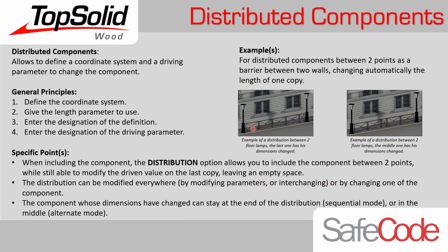You can modify the dimensions of anything in there. So when we bring the distributed components in, they're equally spaced. Every volume is the same width. We can modify that and change the width and give it fixed values. And by giving that one a fixed value, all the other ones will change because they're all equal size.